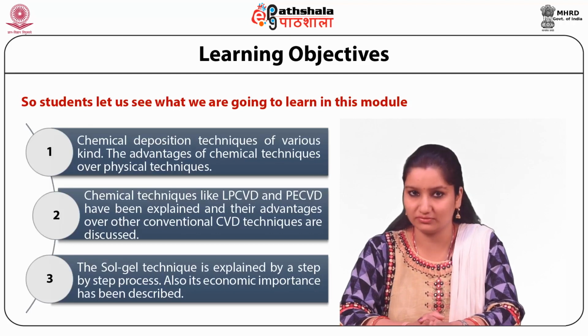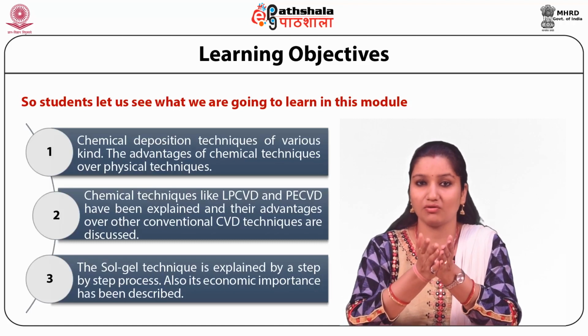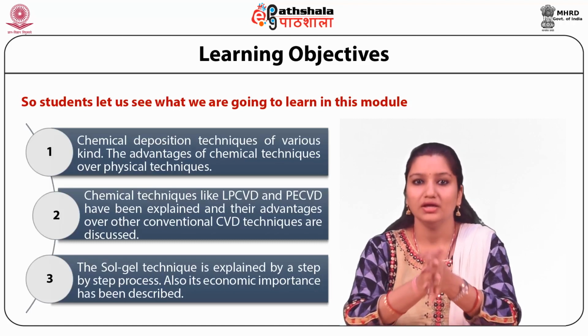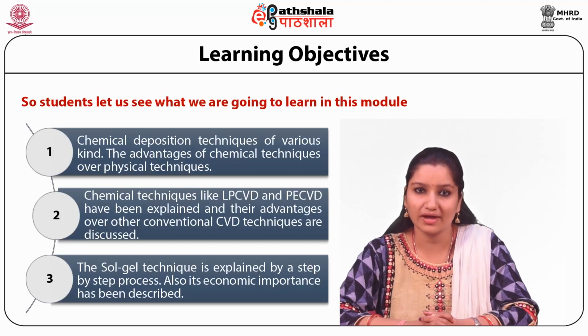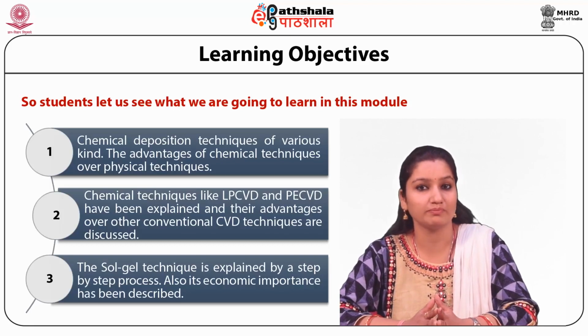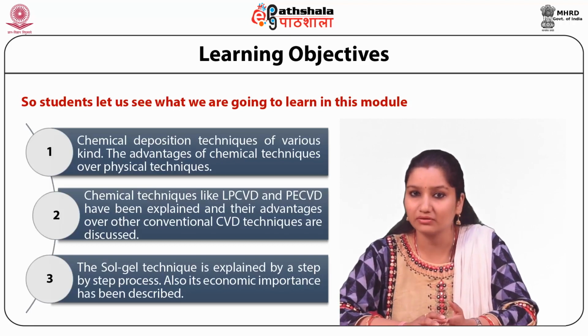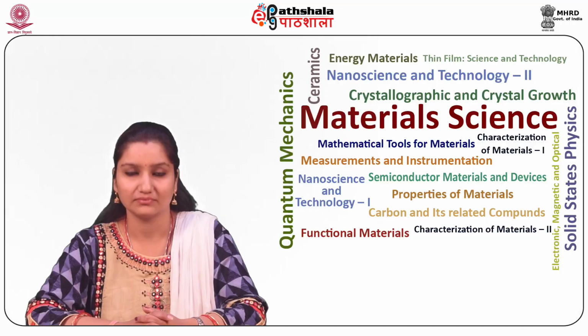Chemical solution deposition, or the CSD technique, which we can also call sol-gel processing, is a convenient and versatile method to synthesize ceramics and glass materials in a wide variety of forms such as powders, thin film coatings, microporous inorganic membranes, fibers, monoliths, and porous aerogel materials.